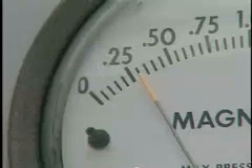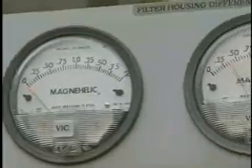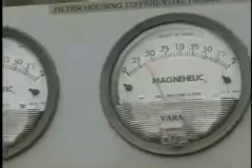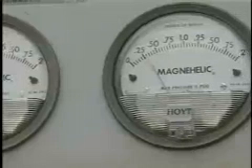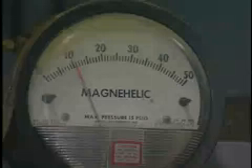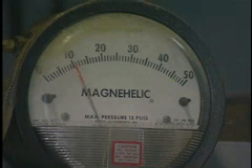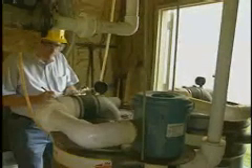The pressure drop across the carbon bed should be evaluated. As the carbon bed ages, it settles and compacts, causing the pressure drop to increase from baseline values. Since old carbon may have less capacity than new carbon, an increase in static pressure drop may indicate reduced performance. An increase in the pressure drop can also be caused by accumulation of particulate matter on the inlet side of the bed. The blinding of some of the carbon granules together with poor gas flow distribution will cause increased emissions.